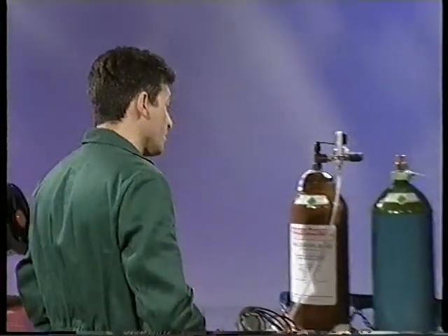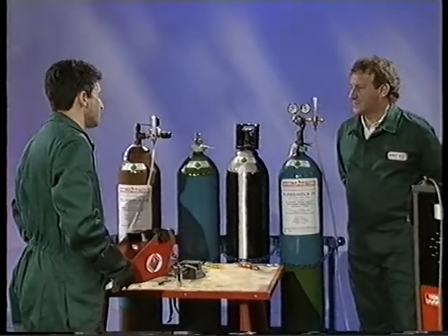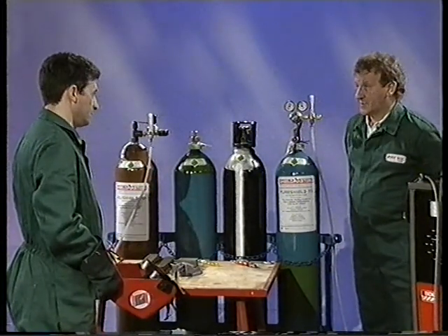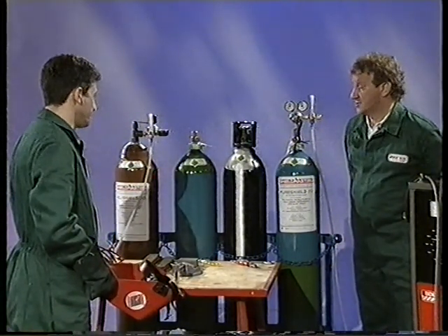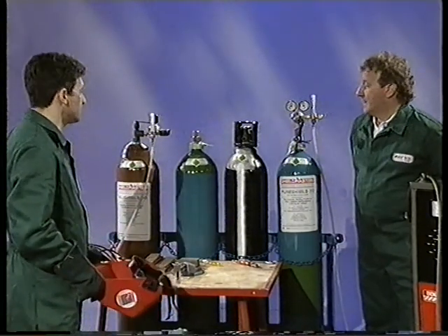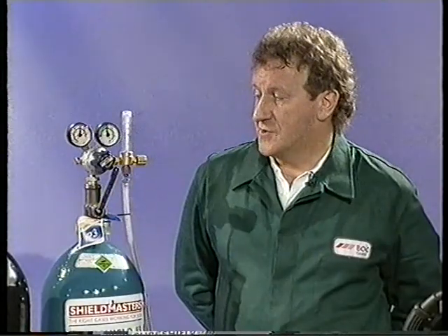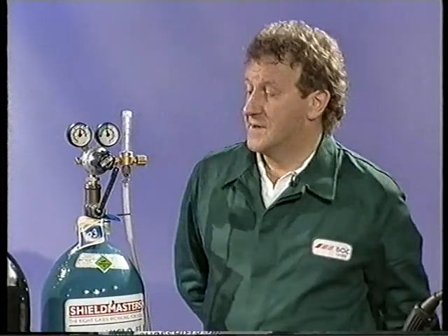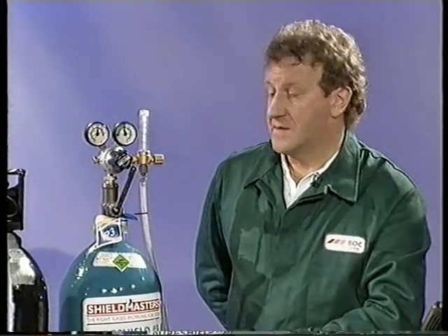Mel, you've made some changes. What exactly have you done? Yeah, the previous welds that we've been doing have all been on a 3-component argon, carbon dioxide, oxygen mixture with varying levels of carbon dioxide according to the thickness of weld that we were doing. We're using rutile flux-cored wire here. Some are developed to run on CO2, but you generally get better results by using a 2-component argon carbon dioxide mixture. Yeah. This is the gas that we've set up.